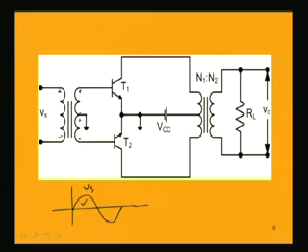Now, as this is the case, the transistor T1, as it is forward biased, if we look into the transistor base, NPN transistor this is, so we have this forward biasing for the transistor T1 in the emitter base junction. So, the transistor T1 will now be conducting, and so collector current will flow in the transistor T1 in this direction. Say, let us consider this as I1.